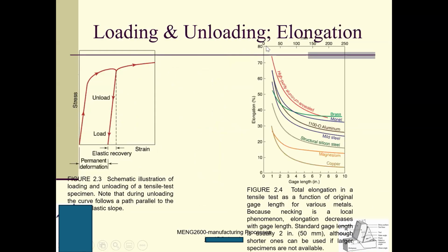So, loading and unloading elongation. This picture is based upon the engineering stress-engineering strain diagram. This is the origin. If we apply the load here, at this point the material enters the plastic region, when plastic deformation occurs.